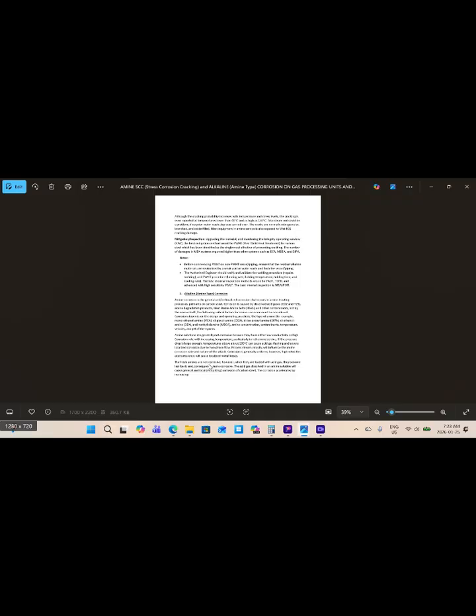Fresh amines are not corrosive, but used and regenerated amine is more suspect to amine corrosion. When loaded with acid gas, they become less basic and consequently more corrosive. The acid gas dissolved in the amine solution will cause general and localized pitting corrosion of the carbon steel.